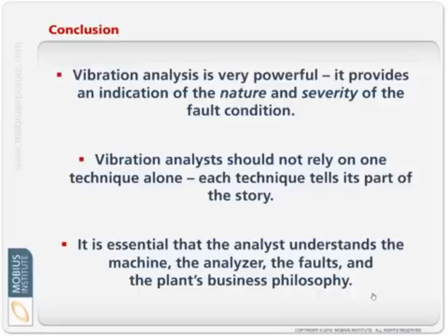And it's worth saying also at this point that there are other condition monitoring technologies, looking at the oil samples for maybe the quality of the oil, the condition of the oil, but also are there any wear particles, any little bits of metal because the gears or bearings are damaged. We can listen and analyze ultrasound, we can perform special tests on the motors, we can look at temperature. There are other ways to assess the condition of the machine.